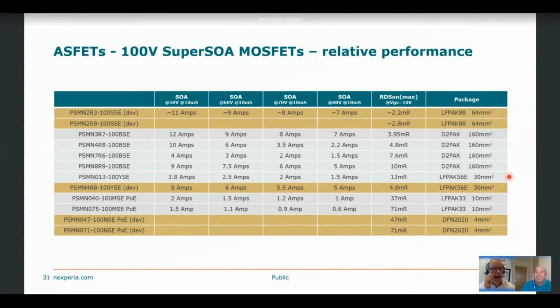Sorry. Where does Nexperia see the lower RDS(on) limit for the 25 volt class in the future, perhaps with chip-scale packaging and as the package losses increase? Yeah, sure. In a 5x6 package, we have 0.5 milliohm. In fact, RDS(on) typical today we have below 0.5 milliohm. We're developing an 8x8 package where we're targeting down to about 0.3 of a milliohm. Of course, in the future, this will continue to get lower and lower.